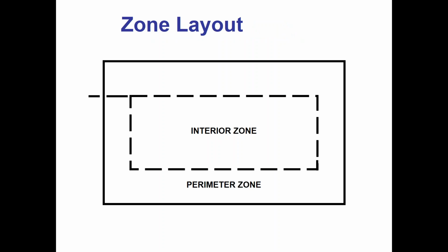All right, so when we're laying this space out, there's some things we're going to have to consider. We're going to try to get this done with one air handler. Let me go back to my laser pointer thing. Get this done with one air handler, or at least one air handler per floor. Now, normally, if I don't have VAV, if I have constant volume systems, meaning rooftops, air handlers, fan coils, things like that, in those applications, we do not want you to use one rooftop unit or one unit for the whole entire building or the whole floor even.